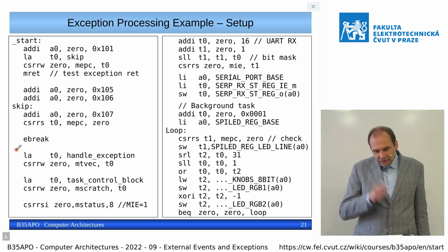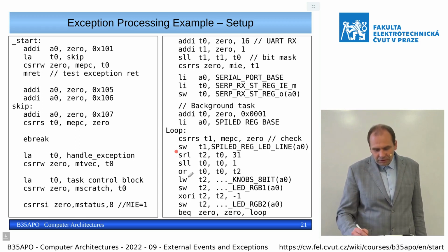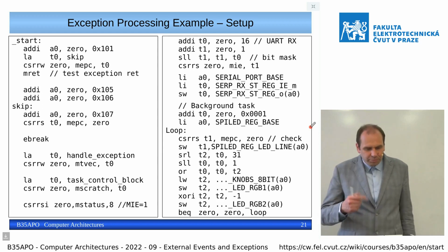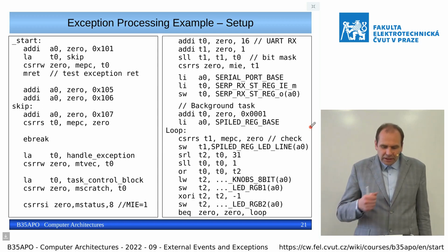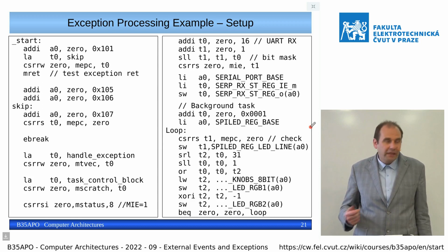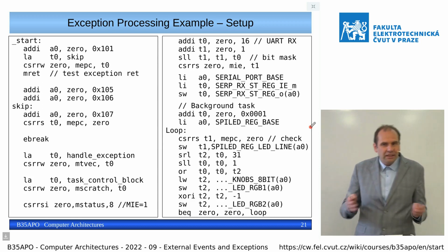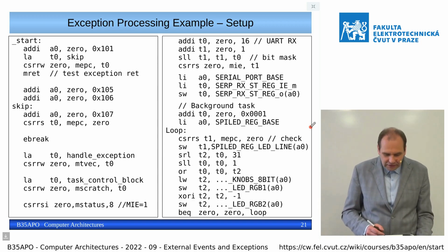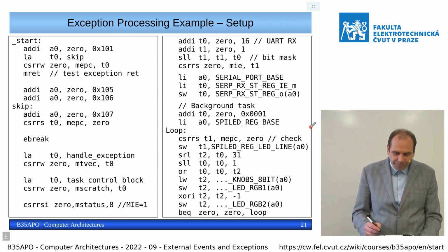It runs in a round. It sets one LED after another, and when a character is incoming, then without polling the status register, it should read it and send it back. If we add line editing and then an operating system and shell, then you can start with the whole operating system from this point.